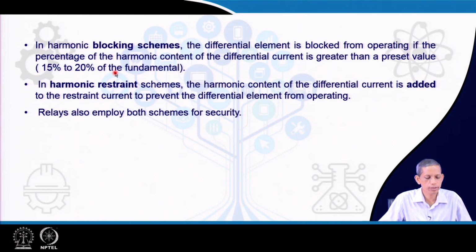This feature is observed in numerous inrush situations as compared to an internal fault. Note that the differential relay should operate only for an internal fault between the two CTs for the transformer protection. But this is an inrush situation, not an internal fault at all, so it should not operate in that situation.